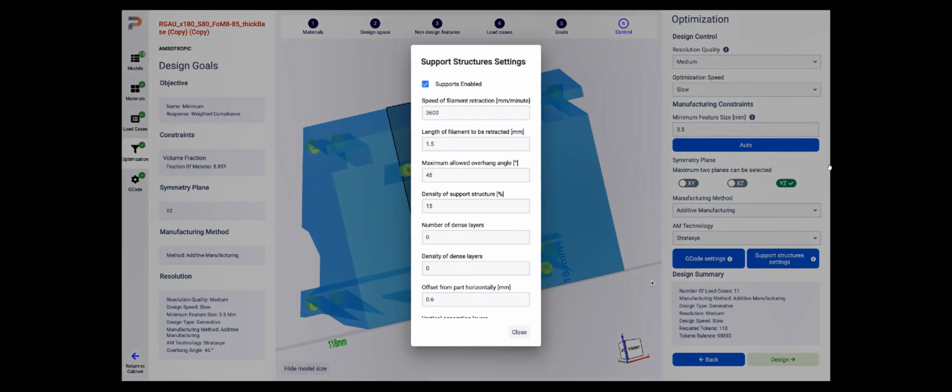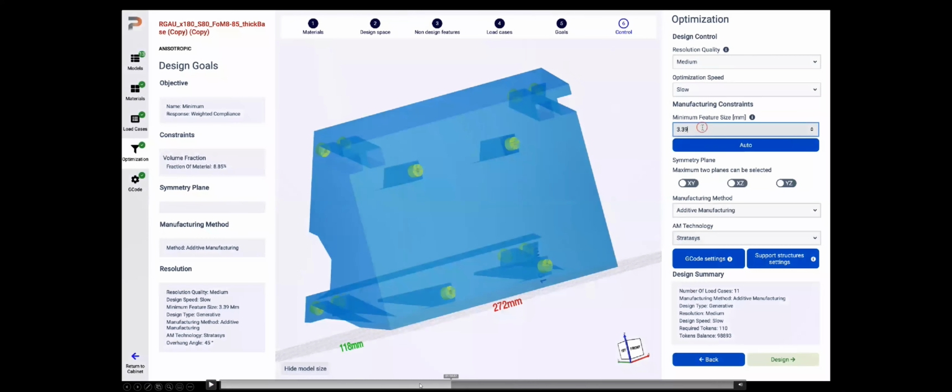If I understand the question correctly, in traditional laminated composites, when you take prepregs, you basically have fixed orientation in all the plane. The advantage of additive is that you can change orientation of the material alignment according to the optimization. So if you could, Bram, run this video a little back, when we see the G-code, basically in plane, even each layer, we can change orientation.